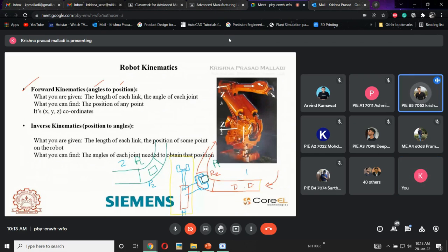It will incline at an angle. See, let me give you one more thing. The length of this arm is some 50 centimeters, let us say. So if the distance between these two is 100 centimeters, is it possible to reach? Now the conveyor and the robot are 100 centimeters apart. The length of the robot is 50, and this is a fixed one. The robot envelope should be 50 centimeters only. Now will it reach the RZ in this condition?